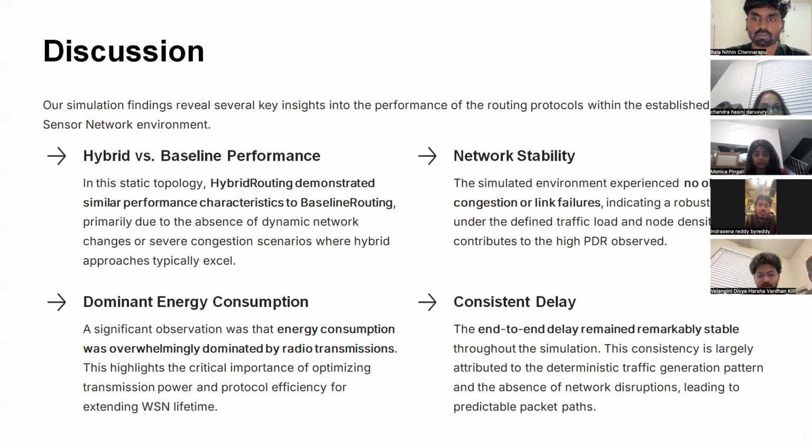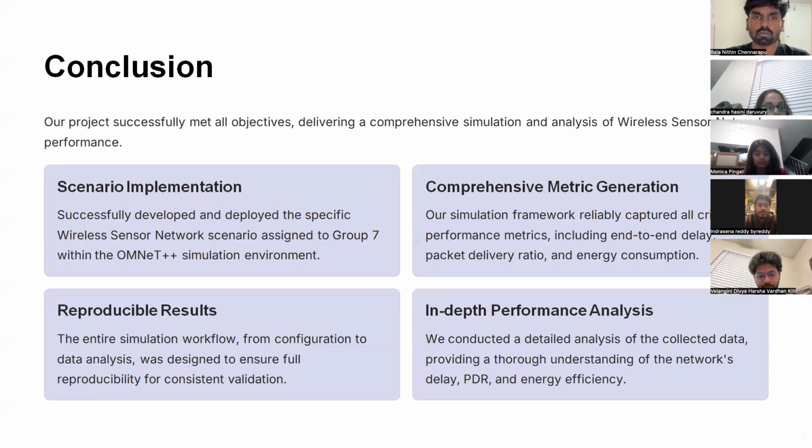Speaking of the conclusion, our project successfully met all of its objectives by delivering a complete simulation and detailed analysis of the wireless sensor network. We were able to design, implement, and deploy the specific scenario assigned to Group 7 using the OMNeT++ simulation environment. Our framework reliably captured all the critical performance metrics, including end-to-end delay, packet delivery ratio, and overall energy consumption.